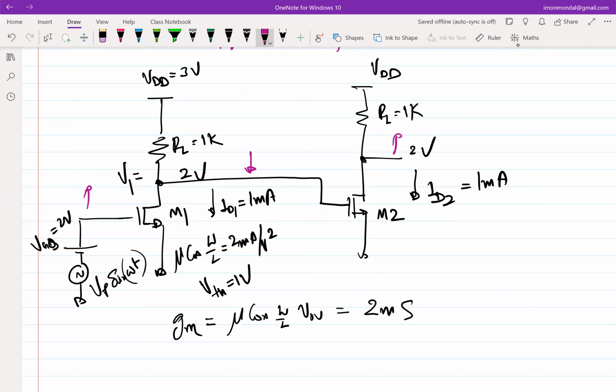When you are increasing the input, which transistor is trying to go into linear and which transistor is trying to go into cutoff? The first is trying to get into linear and the second is trying to go into cutoff, right? So now your job becomes to figure out which one is going faster towards out of saturation, because that is the one that will set your maximum swing. In order to figure that out, what is the next thing that you need to do?